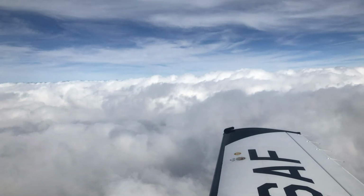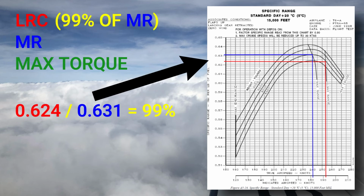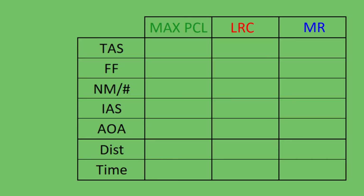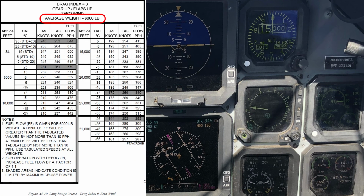The last thing we'll do in this video is compare long range, max range, and max torque cruise performance. As mentioned, long range cruise is 99% range distance of max range, but with a significant time savings compared to flying max range airspeed. To put this to the test, a T-6 was flown in a MOA in order to compare long range, max range, and max PCL performance. In this test, the aircraft is flown at 15,000 feet with about 700 pounds of fuel, which puts the aircraft at about 6,000 pounds gross weight.